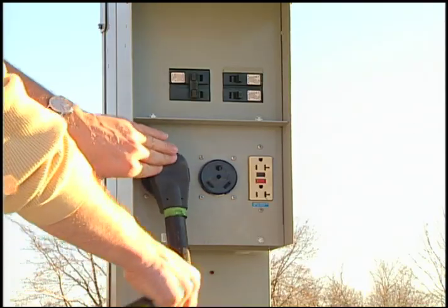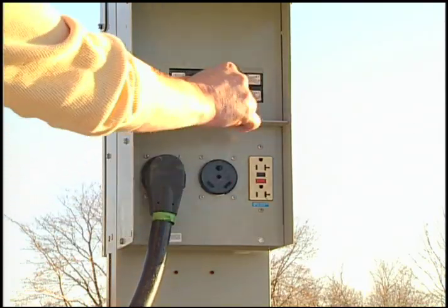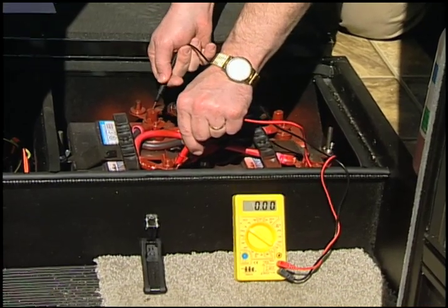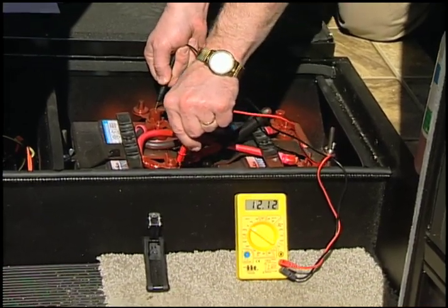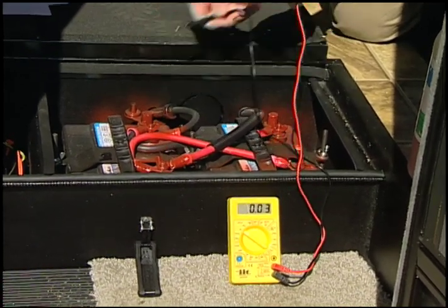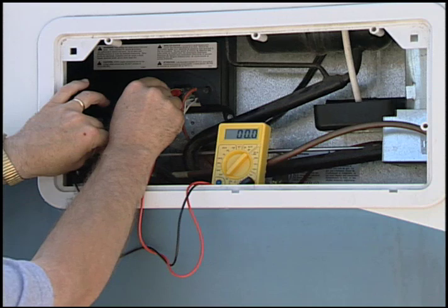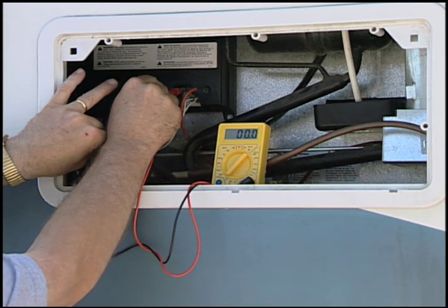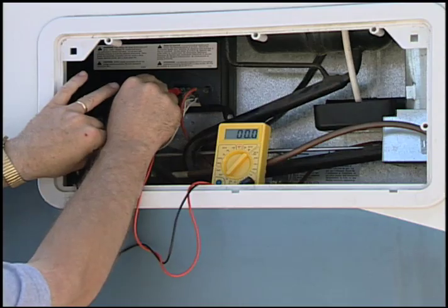Sometimes erratic operation can be caused by an AC ripple into the DC power supply. Clean direct current or DC power is mandatory for high-tech circuits to operate as designed. AC ripple can be measured by a voltmeter set on the AC scale at the main terminal block connections. 6 volts AC or less is acceptable.